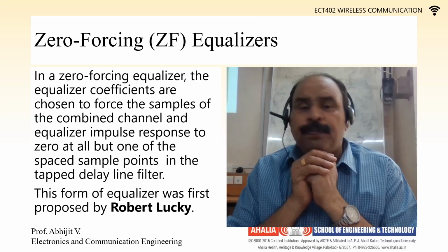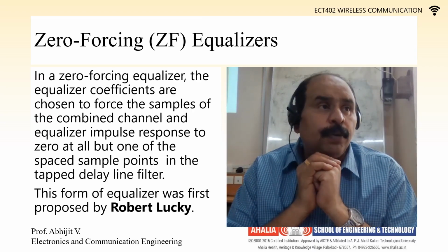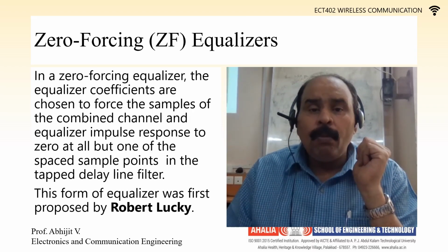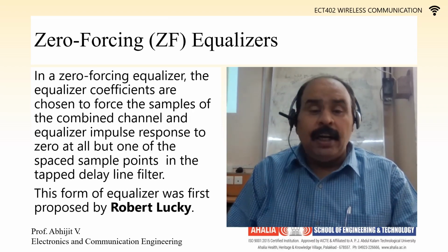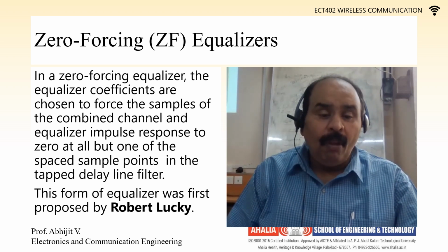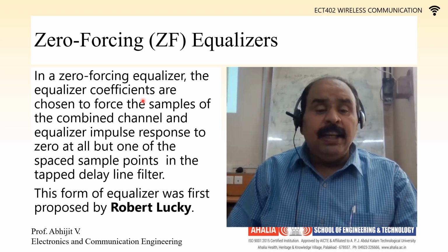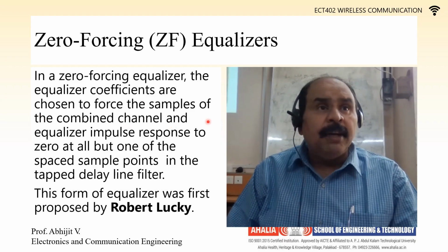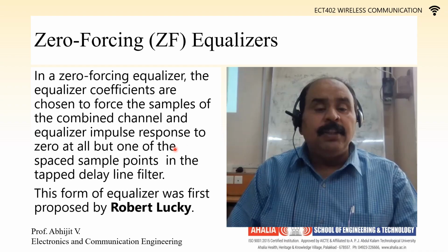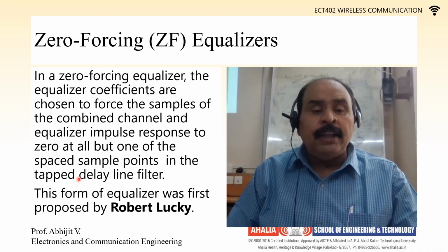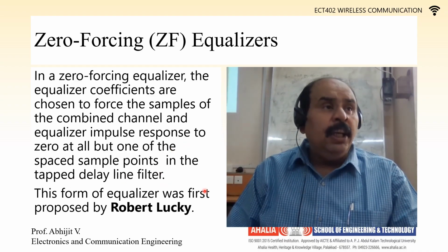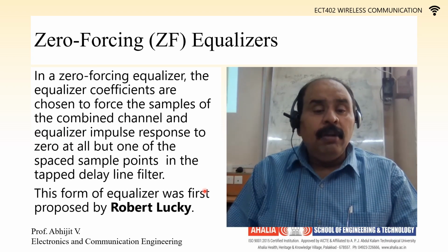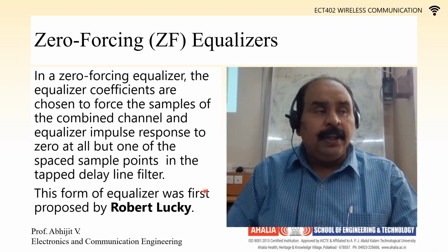Coming to the zero forcing algorithm or zero forcing equalizers. Studying what a zero forcing equalizer is. In a zero forcing equalizer, the equalizer coefficients are chosen to force the samples of the combined channel and equalizer impulse response to zero at all but one of the spaced sample points in the tap delay filter.